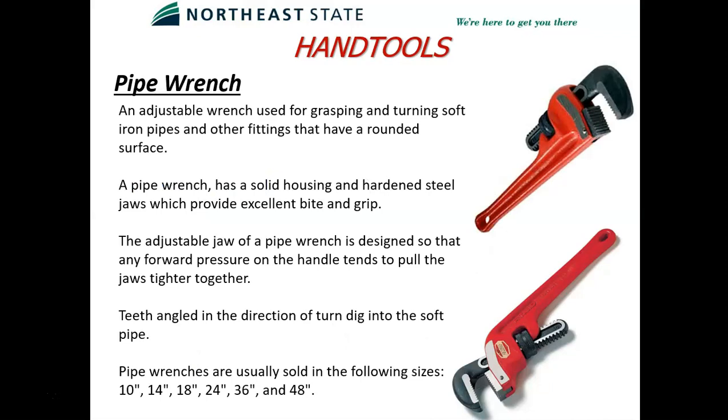So pipe wrenches. Pipe wrenches are used basically for piping and conduit running. There's different angles, different lengths of pipe wrenches. They have serrated teeth in reversed angles, so they grip only in one direction. The head slightly moves. You've got a knob there that turns, and it opens the jaws, it closes them.